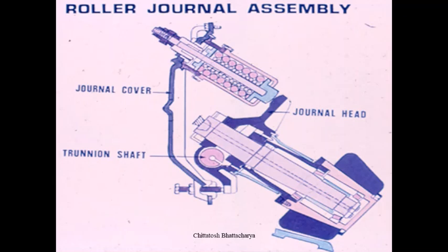The primary air temperature, whatever we get at the inlet of the PA system, goes up to 340 degrees centigrade. Beyond 340, if we try to increase it, then there may be more dry flue gas loss through the boiler. So naturally, we try to balance the drying of coal with the degree of heat available within the PA system.